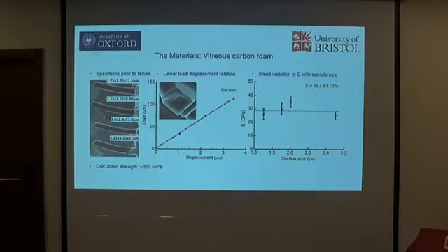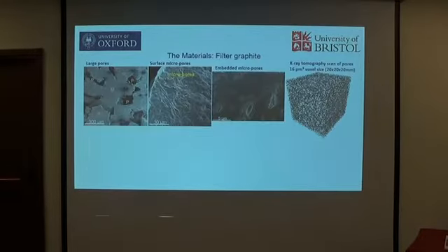Here's a typical load displacement curve. It always fractures brittle. So you can see the brittle fracture mode, and you calculate the elastic modulus and the flexural strength. Actually, it's the same behavior and a similar value as what you measure from a macro scale. So that means that this technique is trustworthy and also calibrated on single crystal silicon. So that gives me the basis for my future data.